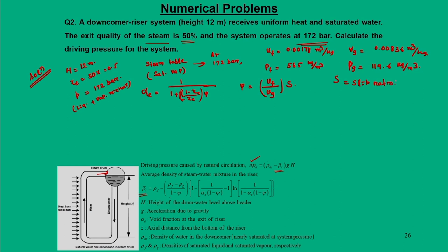I mentioned that the steam in this riser is a mixture of liquid and vapor. So, vapor travels at a faster rate. So, that means we say that the slip ratio is about 1.2 times higher. So, for this factor xi is represented here. Now, we take this as 1.2 and we know Vf and Vg. So, xi number is 0.254, and when xi is 0.254, xe is 0.5, this will give alpha e. When you insert this value, we get alpha e is equal to 0.8.